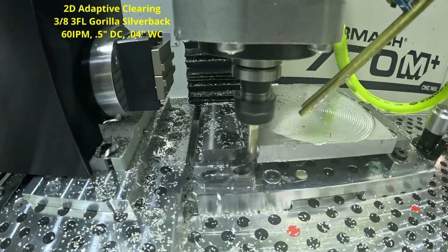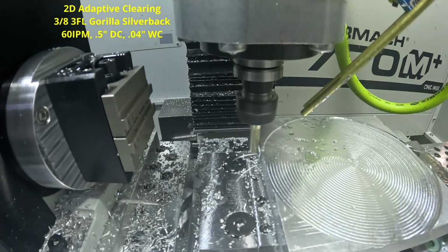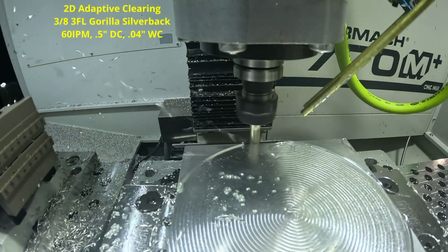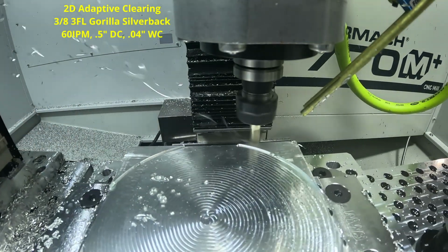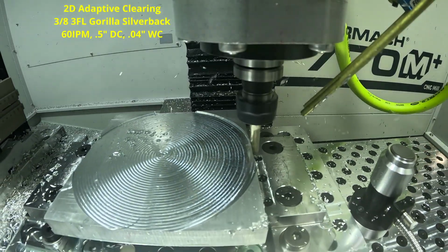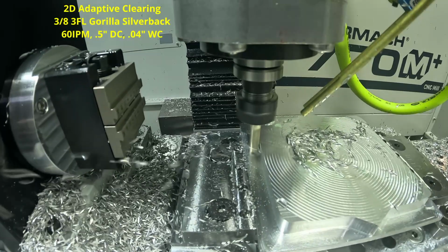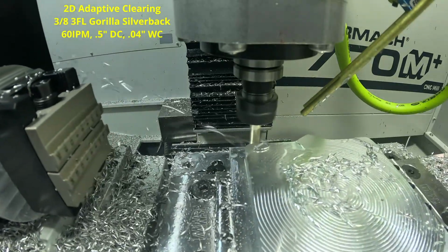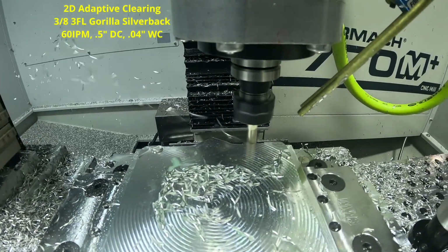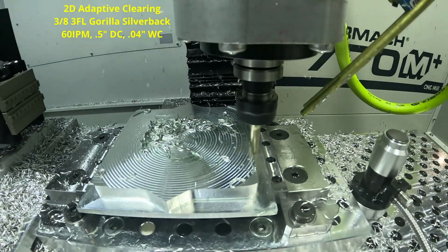All right, so here's our 2D adaptive clearing, same 3/8 3-flute Gorilla Silverback end mill, 60 inches per minute, half an inch for our depth of cut, and 40 thou for our optimal load or our width of cut. Again, we'll jump through the toolpath here to the interesting portions as it is long, and we're really again just removing the material that is around the outside of the shield. And there again you can see that beautiful surface finish from the spiral toolpath.